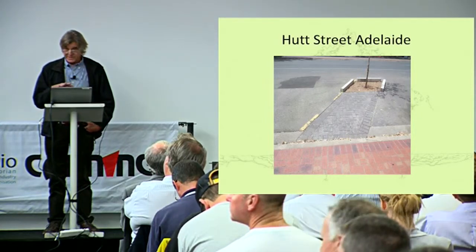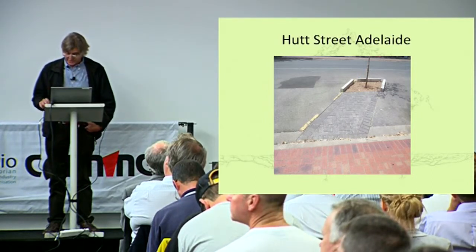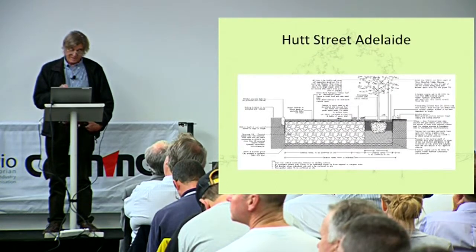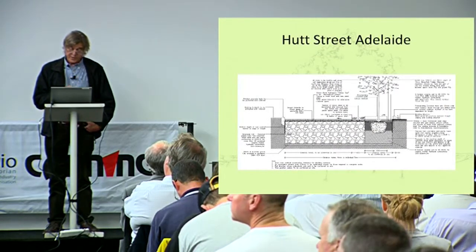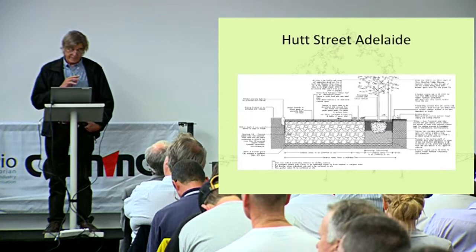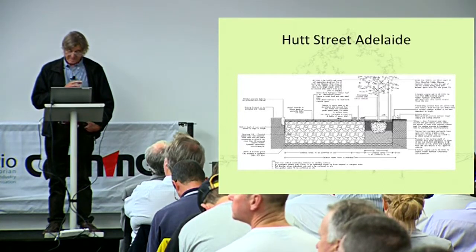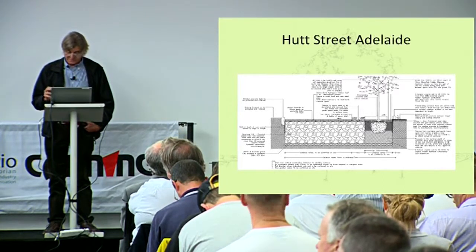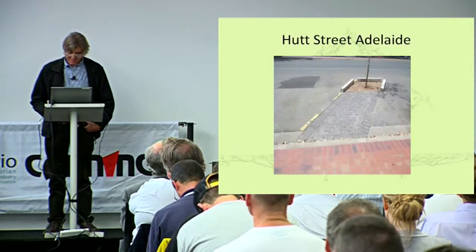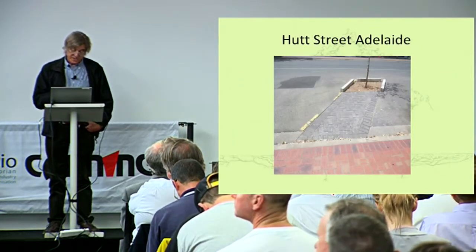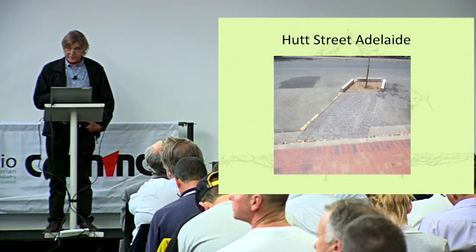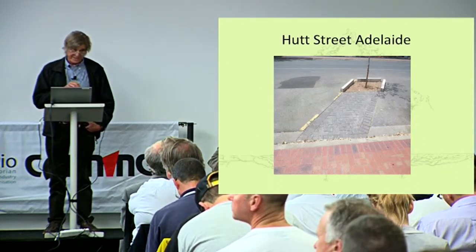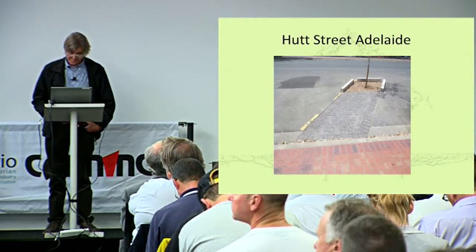So that was retrofitted to some existing trees, and also some new tree pits were installed with structural soils with permeable paving over the surface. So in that sort of situation, the permeable paving extends into the water table itself, so the water can infiltrate down into the tree pit.